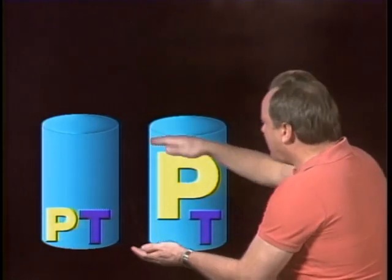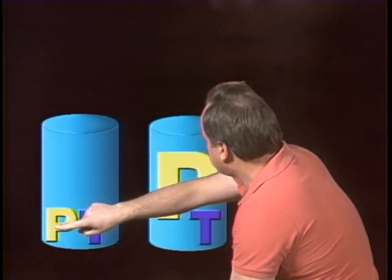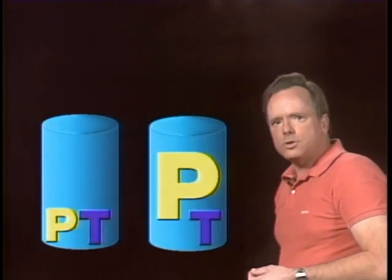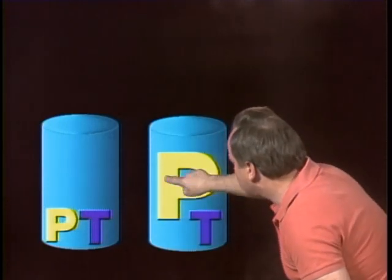How about that? This time, let's you and I take a look at a liquid. And the thing you need to know about a liquid is that a liquid is not compressible. You cannot compress a liquid. That's the principle that hydraulic systems work on. Instead of compressing, the hydraulic system moves things out of the way. You can't compress a liquid. So if you have a confined container and you keep pumping more stuff into a container and it's got liquid in it, the pressure is going to increase dramatically.